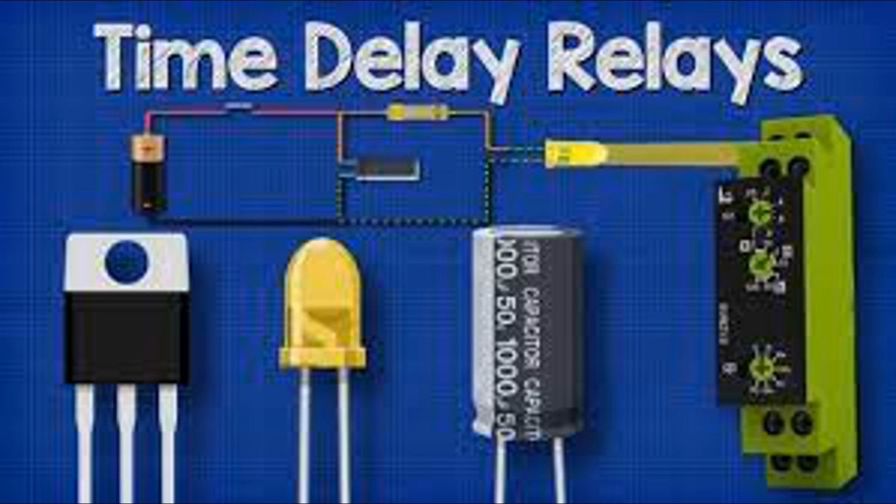Lighting control. Relays are extensively used for controlling lighting systems in smart homes. They allow for the remote switching on, off, dimming, and scheduling of lights throughout the home. Relays can be integrated with motion sensors, light sensors, or smart switches to automate lighting based on occupancy, ambient light levels, or preset schedules. They enable energy-efficient lighting solutions and enhance home security by simulating occupancy when residents are away.